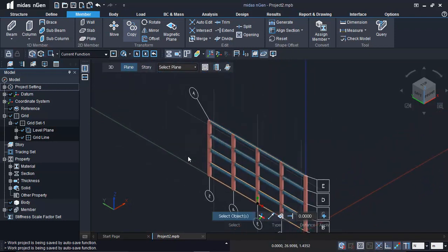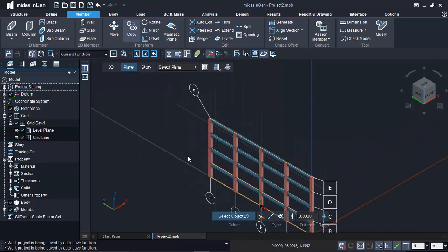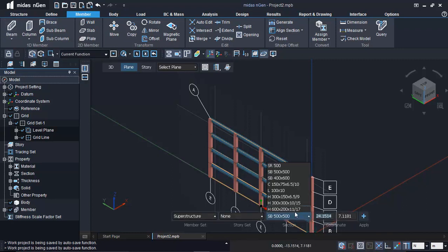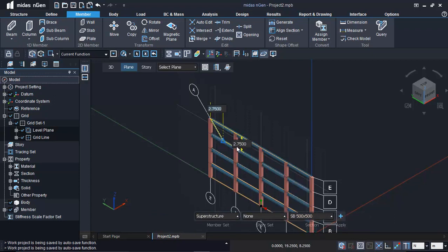So now one of the advantages of the plane view is that if you want to model some bracings or anything, then you can keep working in the plane view. You can work in the plane in any direction. So maybe if you want to work in the vertical plane, then you can just choose the vertical plane. And when you want to generate the bracings or the slanted beams, you can just use the vertical plane, and then you can keep on generating the data along any direction.